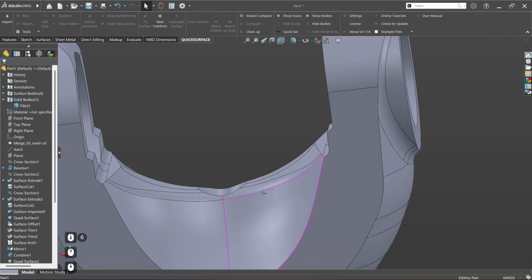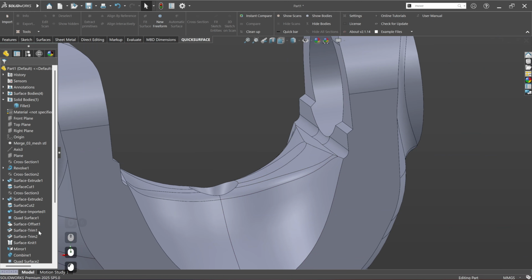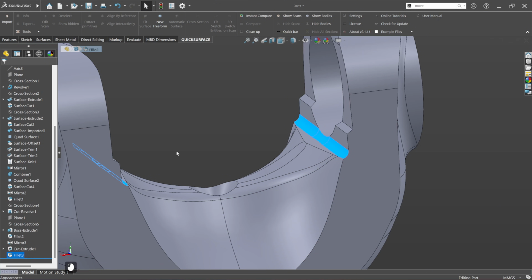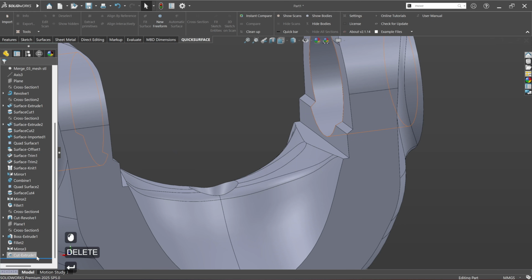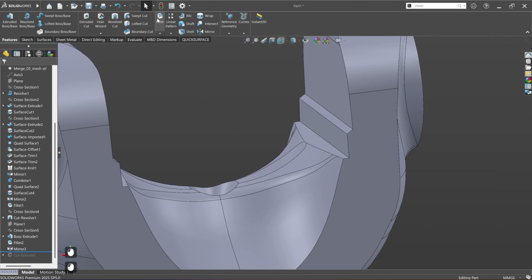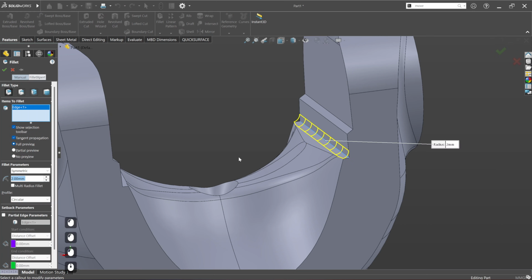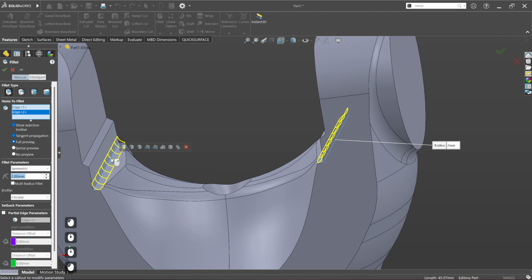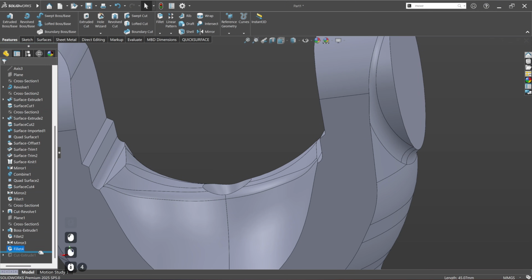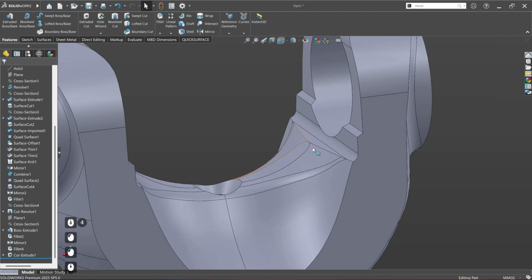This fillet is not what we would like to see here. So in order to make it proper, let's get rid of this fillet. Let's roll back before we created this opening for bearings, and add fillet at this point right now. Okay, and then just roll back, and we can see that it's now a completely uniform fillet. This is what we wanted to achieve here.